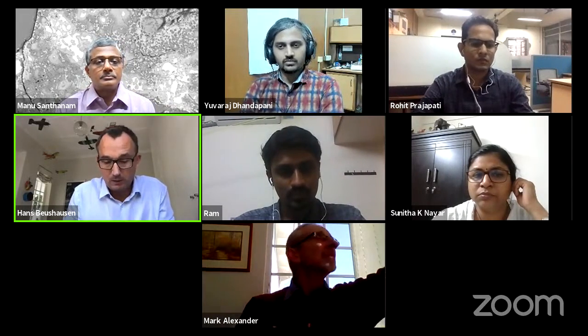The third presentation from Lepocho and Cadimo spoke about the effect of masonry rubble as fine aggregates on concrete properties. So here again, we used construction and demolition waste, but not a concrete, but we crushed down the clay bricks. And what was identified was a strength gain and also a slightly improved durability, especially at higher water binder ratios.